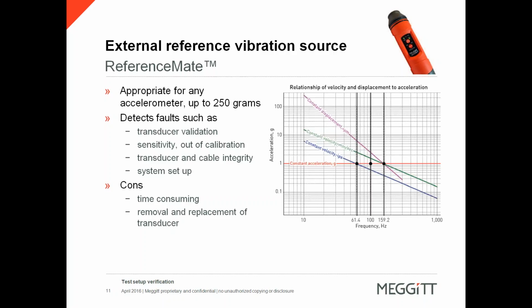Would you like to expand on this, David? Yes, what I can add is this test method is sometimes impractical, since it does require the transducer to be removed from the test structure and mounted on the vibration source, which may not always be practical or accessible. However, it may be the best method to verify the complete system for an important non-repeatable test.